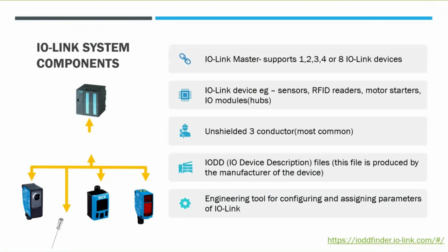And you can see on the left, that's an IO-Link master block, and that's pretty much how the communication channel looks like, with sensors at the bottom, which are going to be talking to the master block, and that communicates it over the field bus levels.